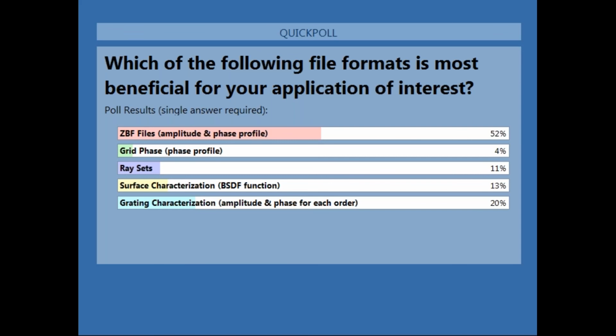Sure. So the far field exact function basically allows you to calculate the field at any point in the far field in free space. So it's really only for free space propagation. So if you just want to see where your light is focusing, if you do the lens simulation, you just want to see what the focal spot is in free space, you can do that with far field exact. And we have a lot of examples online that show you how to do this. But what it doesn't allow you to do is propagate it through a lens system. And as you can see with a lot of what Reza was doing, it's not enough to just assume free space propagation. He needs to further optimize the lens system. So this is really where OpticStudio is ideal for that.